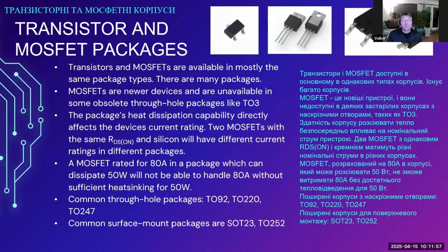Just because a MOSFET is rated for a certain amount of current doesn't mean that you can actually use it at that amount of current. Always pay attention to the actual heat sinking capability surrounding the MOSFET. And that is more or less a mechanical issue.